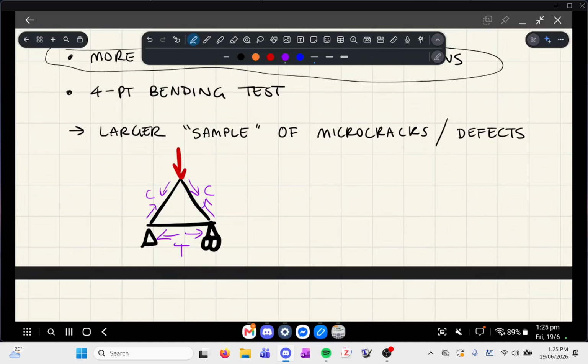But we haven't picked the material or specified a material yet, right? But generally, these trusses are not made of concrete. Now, again, that's not a hard and fast rule, but a lot of the time trusses are more well suited for something like steel or something like timber. Because remember, if you think of a material curve for steel, this is stress versus strain.